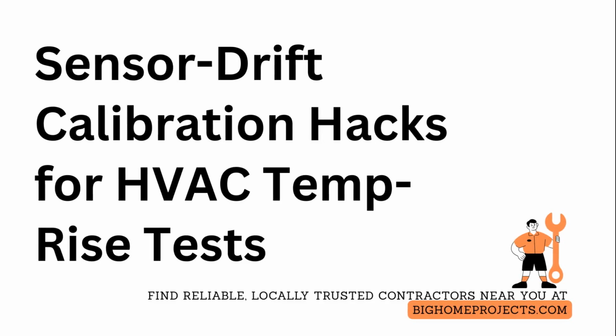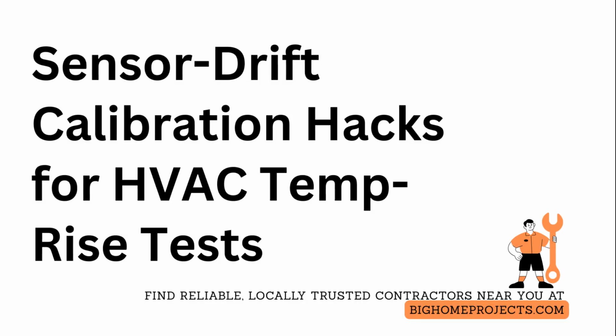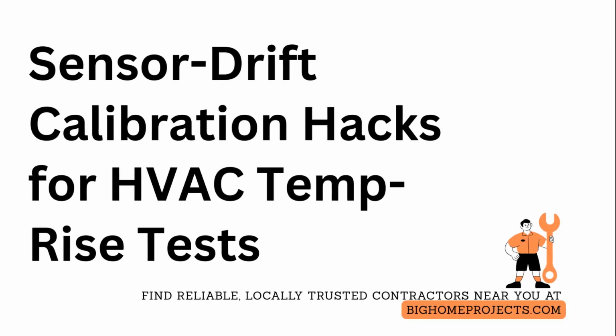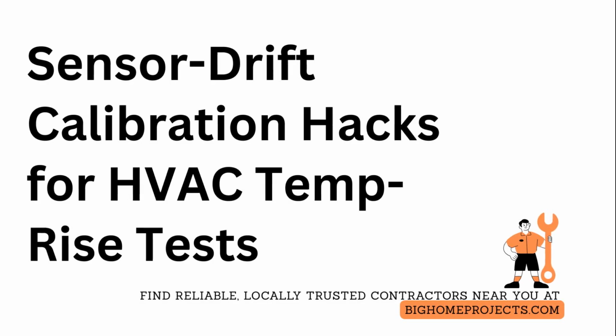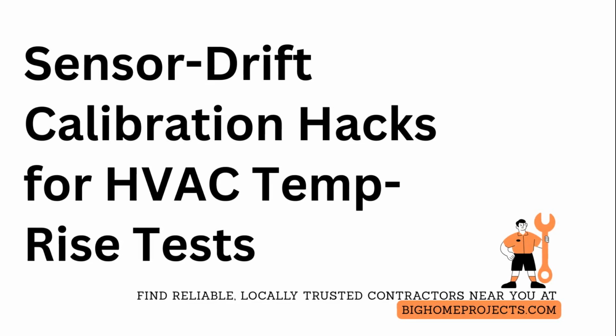The HVAC temperature rise formula tells you airflow in cubic feet per minute by dividing heat input by 120 times the measured temperature rise. Use it every time you test airflow to catch undersized ducts or poor blower performance.